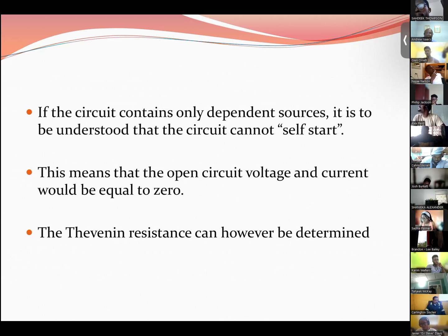What is that principle I'm talking about? If you have a voltage source and you connect it to a circuit and find the corresponding current that flows into the circuit, then that gives you an indication of what the resistance of the circuit is. Or if you have a current source and you apply that to the circuit and find the corresponding voltage, then again, you can find the resistance. So that's the principle we're going to apply.